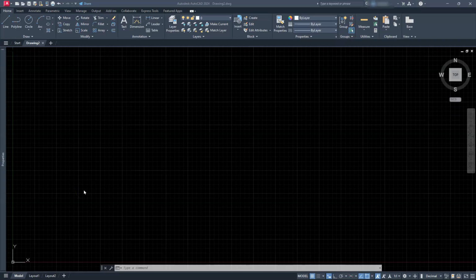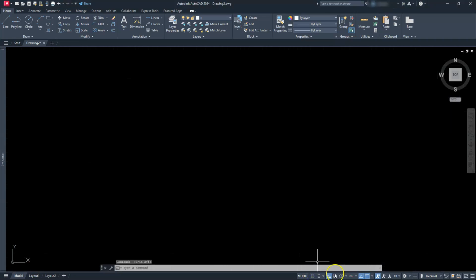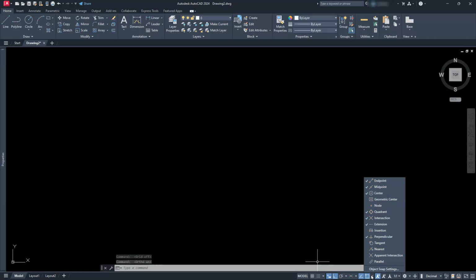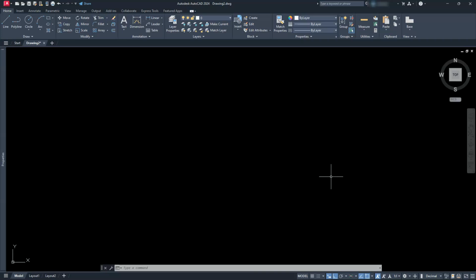Okay, so let's go ahead and do our normal stuff that we usually do. Let's go ahead and turn the grid off. Then we're going to turn our ortho on. And then let's go ahead and check our running O-snaps. So these are going to be the ones that I'm typically going to use. Alright, so now let's start drawing, right?